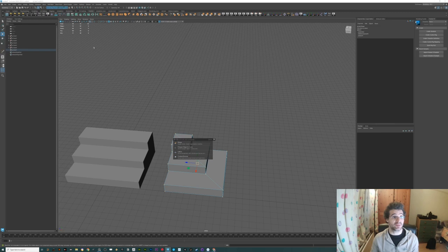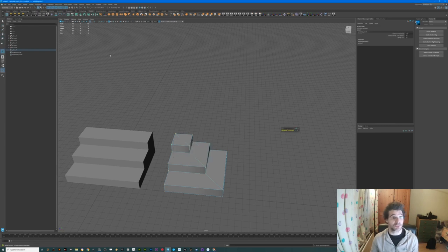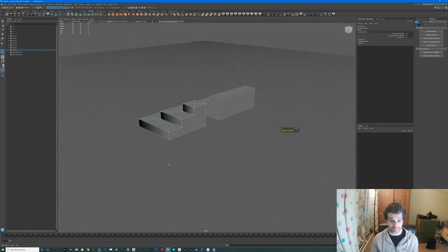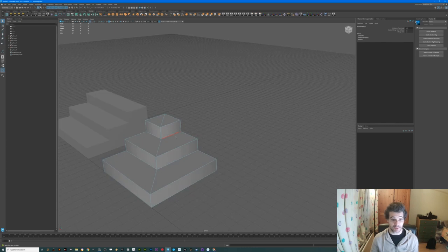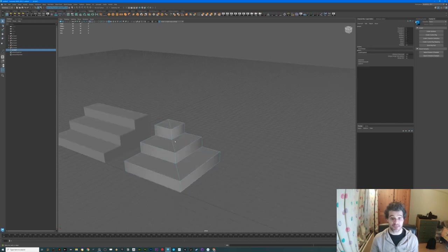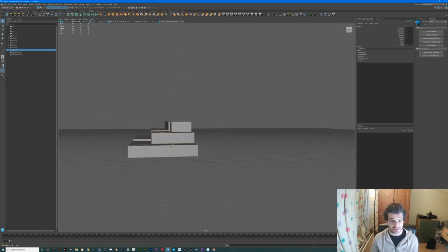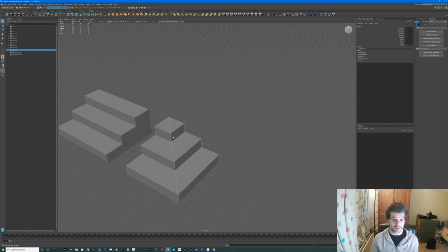As you can see, we have 32. I press merge, and it goes back to 20. We have something a little strange with the shading. This means that our normals aren't completely flattened. So if I come here, press Shift middle mouse click, Shift right mouse click, I go here to soften harden edges and just select harden edges, and now everything is fine.